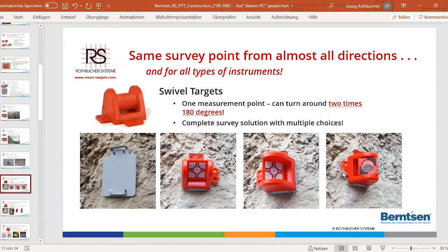Also very important: if someone wants to work with robotics, we offer a complete prism system. And you use the right offset; here is offset 0 with the target reflector. On our prism system, the offset is written. On our biggest prism, the RSMP 380, the offset is -60.9, and for Leica +17.5. And the one who is using Leica knows it's the button for mini prism.